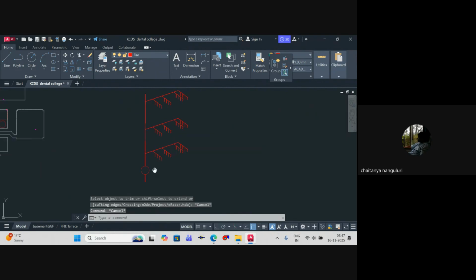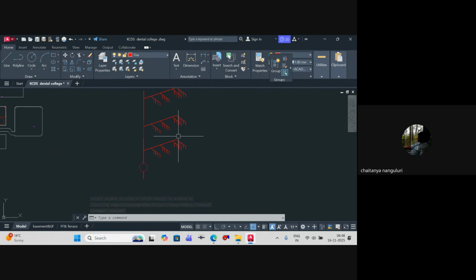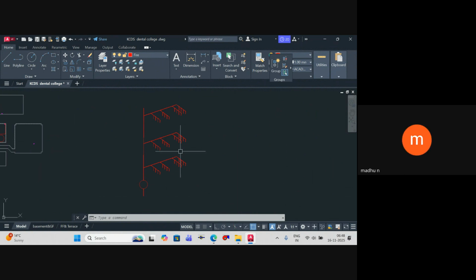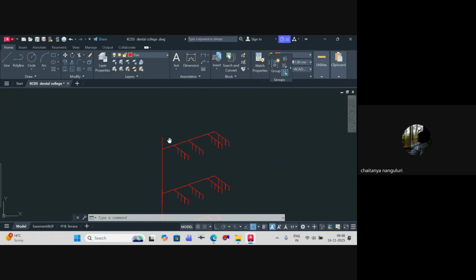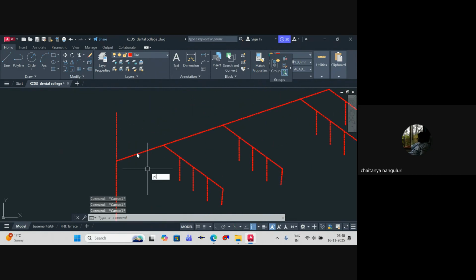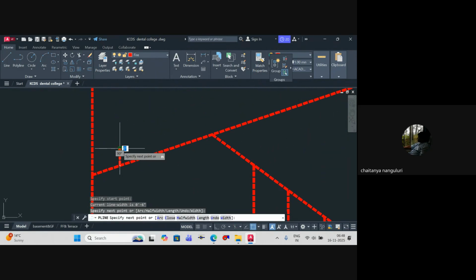This alarm valve will tell you that some sprinkler in this entire riser got broken. But don't you think I have to connect it to the PA system or anything? Yes or no? It has to be connected. Obviously, I have to tell everyone that there's a fire in the building, please escape. So for that reason, we have a flow switch, and we'll obviously know which floor or which zone it is also. For that reason, we have a flow switch in every line.